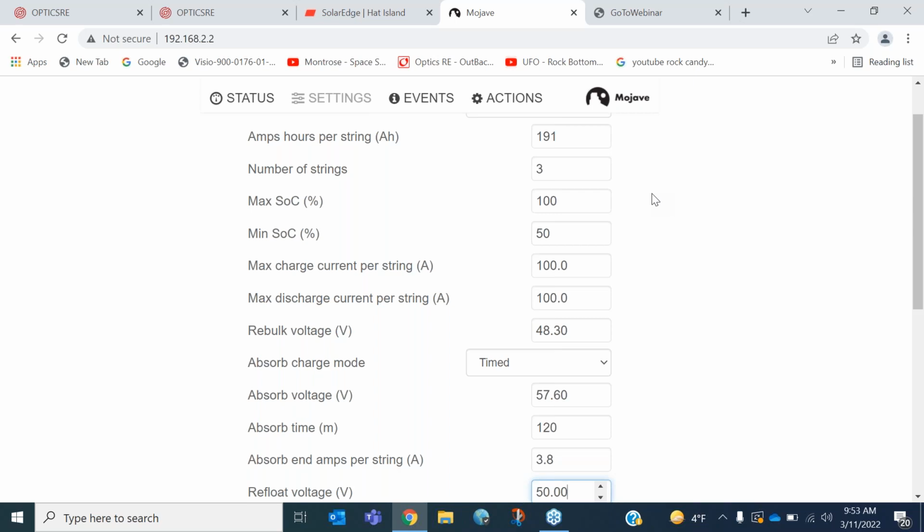I think it's asking if the battery gets used overnight, will the grid tie inverter, quote unquote, wake up the Mojave inverter in the morning when the sun comes up? We have a low battery cutout and a low battery cut in. We will stop inverting when we hit low battery cutout, and that doesn't shut the inverter off. If you're on the grid, it's going to be passing through and the solar will be alive. If you happen to be off grid and low battery cutout happens, we'll stop inverting.